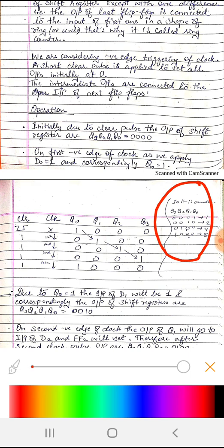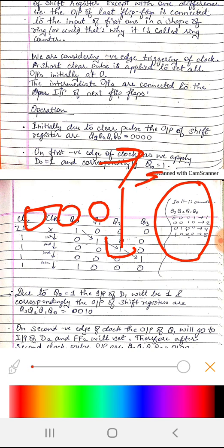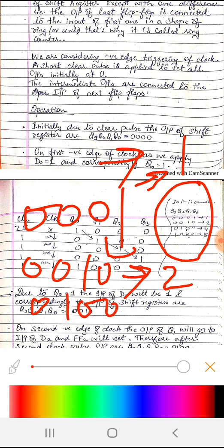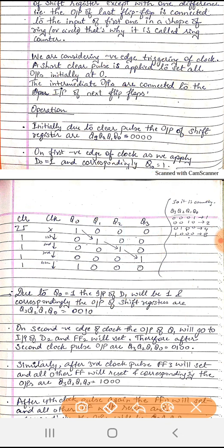As we can see here, the Q0 becomes 1, and if I convert it into binary 0001, this is our LSB, we are filling the LSB first. So it will become 0 0 1 0, represented in binary. If I convert into decimal, it will be 2. 0 1 0 0 would be 4. Similarly 1 0 0 0 would be 8. So this is how a ring counter would count,